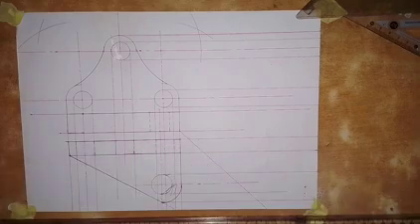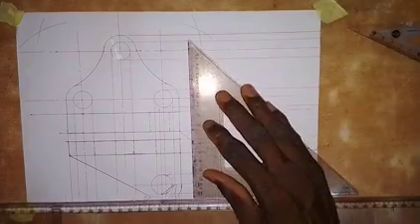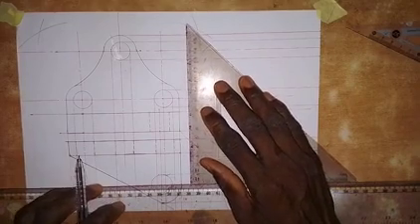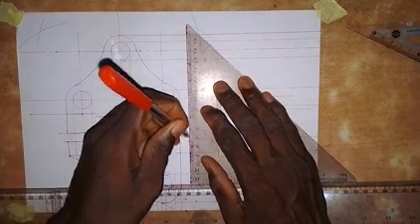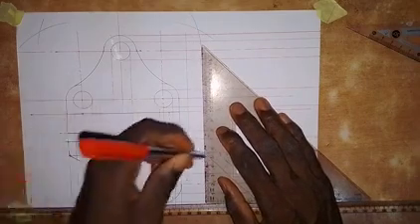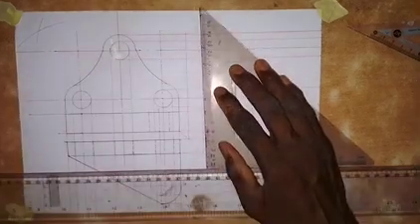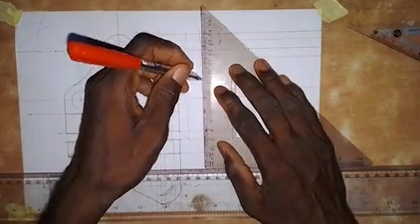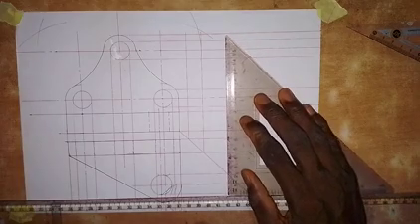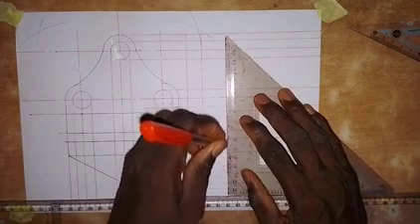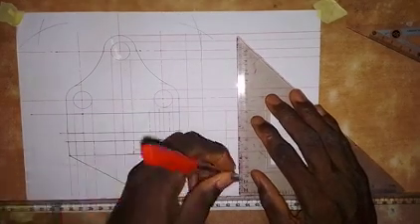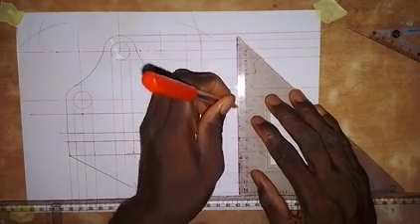Alright, so then I'm going to be transferring these distances. Where the inclined lines intersect the horizontal lines that we drew from the plan, we draw a vertical line up here. So I will come here also, and draw a vertical line. So this line will go up like this. Alright, so then from this point, I'm going to draw a vertical line. It will just be within this part here. And from the center line, I will also draw a vertical center line here. Okay, so this is okay.